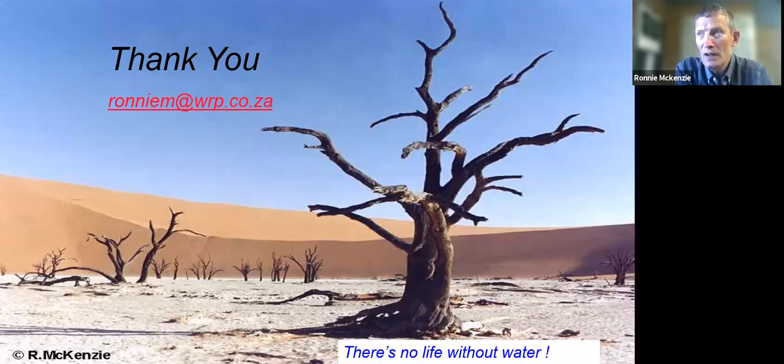And we typically go for the simplest. We would normally go for time control, or we often use the flow control controllers, but in a time control mode, because you can set the pressures on different days according to a time profile. We quite like a profile for Monday to Friday, and then a different profile for Saturday and Sunday.